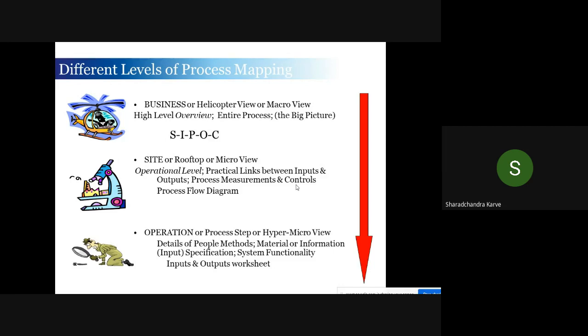overall process. So if you look at, say, I am having a polypropylene plant, what will be the inputs for making polypropylene, and what will be the outcomes? You list down everything. Even if you are producing a waste, you write down that waste also, and what the inputs are and what the agencies are which are supplying you that input. Then at the next step, it is a process flow diagram, PFD, where you see how exactly the material is moving, so that going forward to the third step, you can map what the inputs to the reactor are, and then the inputs to the next process, etc., and what the final output is at all steps.